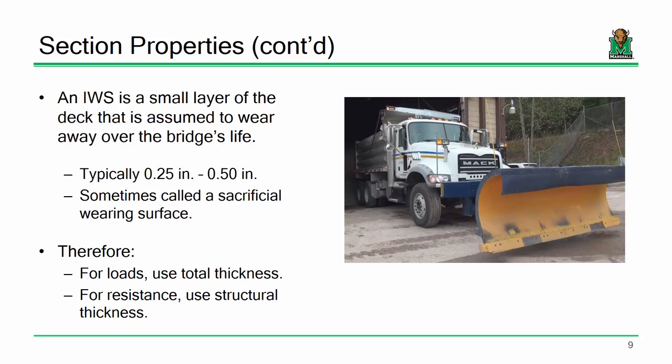So to give you an example, when we're out there in the field pouring the bridge deck, we might pour an 8.5 inch thick concrete deck. But over time, we're going to assume 1/2 inch of that's going to go away due to it getting scraped off, due to wear and tear, and what have you.